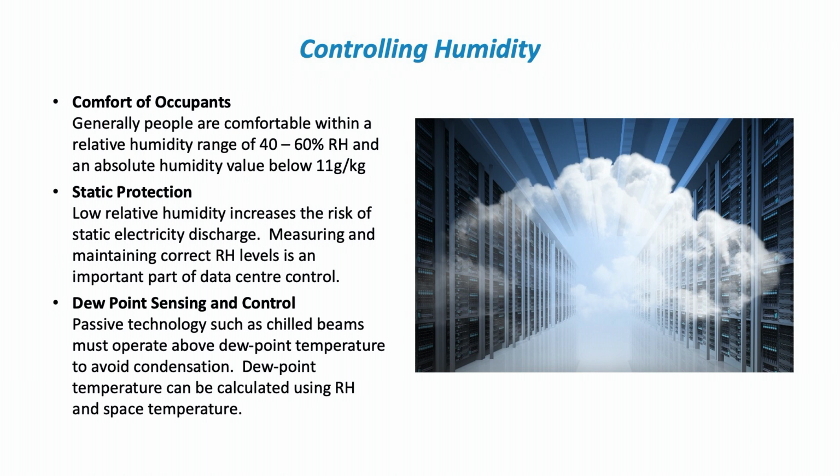If your room is at 22 degrees C, but your relative humidity has dropped down to about 30%, you are still going to have people who feel uncomfortable. That level of humidity is quite possible to happen in the winter. You provide a lot of heating, it drops the relative humidity as a result. People get itchy eyes, sore throats. If you have conditions such as eczema, it will exacerbate those as well. So we need to be mindful of controlling humidity.